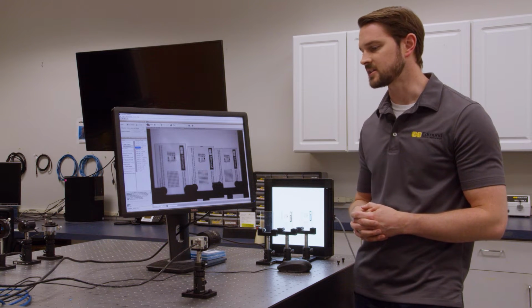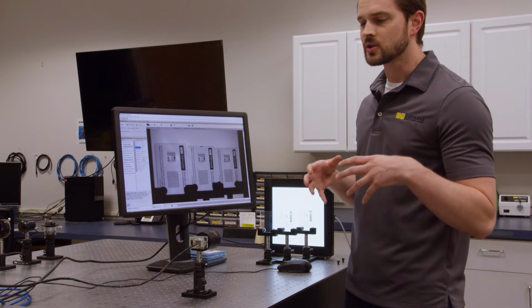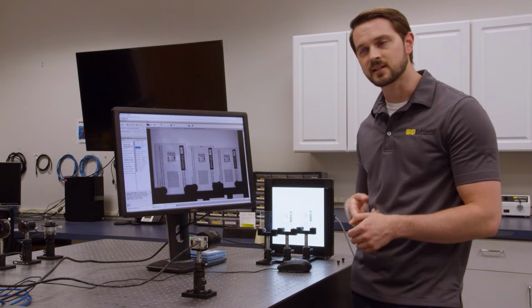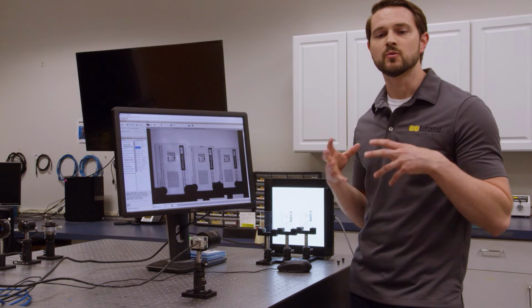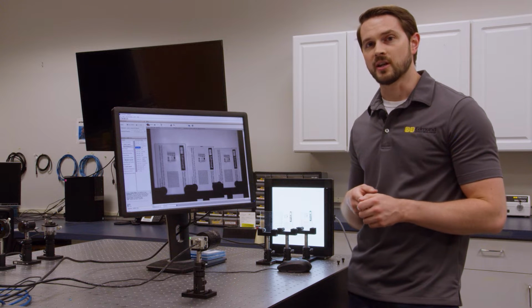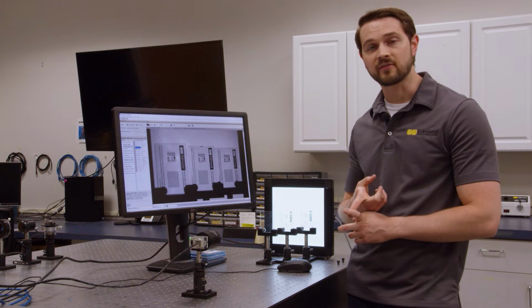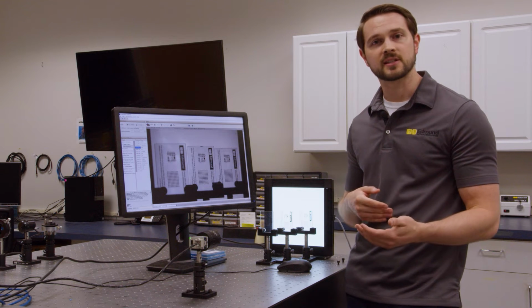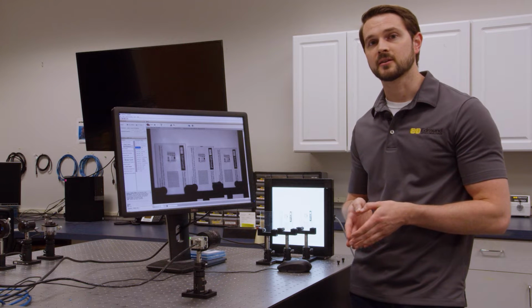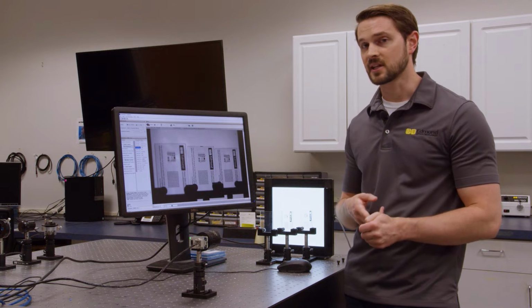So let's go ahead and dive into this lab. As I mentioned, we're going to be talking about two things, f-number and color. Once you've gone through your specifications and decided this is the lens and this is the camera that I want, and you thread it all together, the only two things that you can change in your system to impact your performance are the f-number and the color. Your working distance is already set because you ran your calculations and know that you need to be so far away to get a specific field of view. There's nothing else you can change other than purchasing another lens besides these two things.